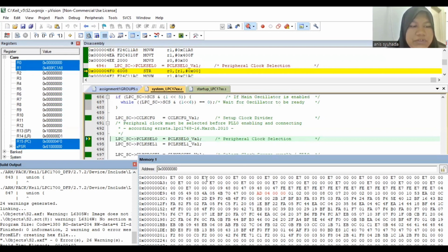The loop termination is confirmed: the loop terminates correctly after all data has been transferred, preventing any unnecessary iteration. Verify that the loop termination condition CMP R3, #26, accurately detects when all data has been transferred.